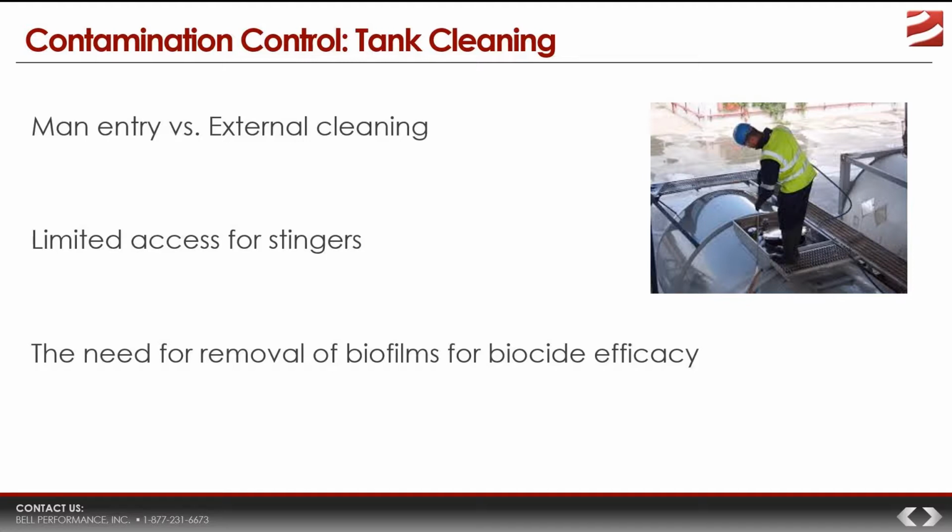But as good as you can try, as complete as you think your tank cleaning efforts are, just like with water, it is virtually impossible to get all or even most of the biofilm out of that tank. While a lot of it is in that plus or minus 15 degree zone, that bottom dead center that we talked about, that strip is really the limitation for how far the typical tank cleaning stingers can reach. It can't get all that other biomass out there.